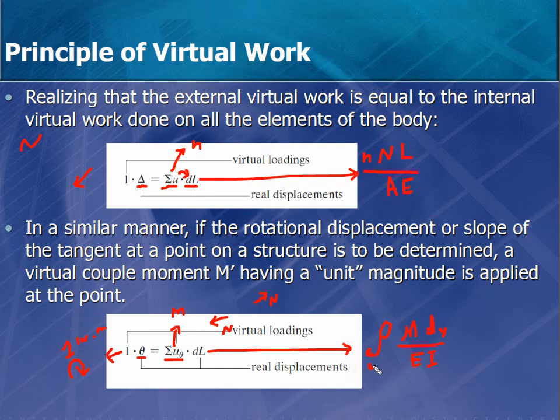And this is going to be integrated over the length of it. So I have small m, capital M dx over EI integrated over the length of the beam.